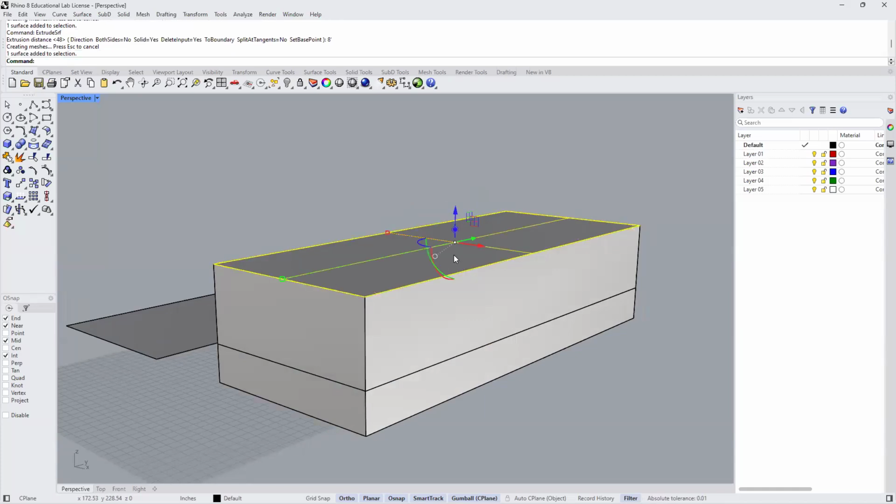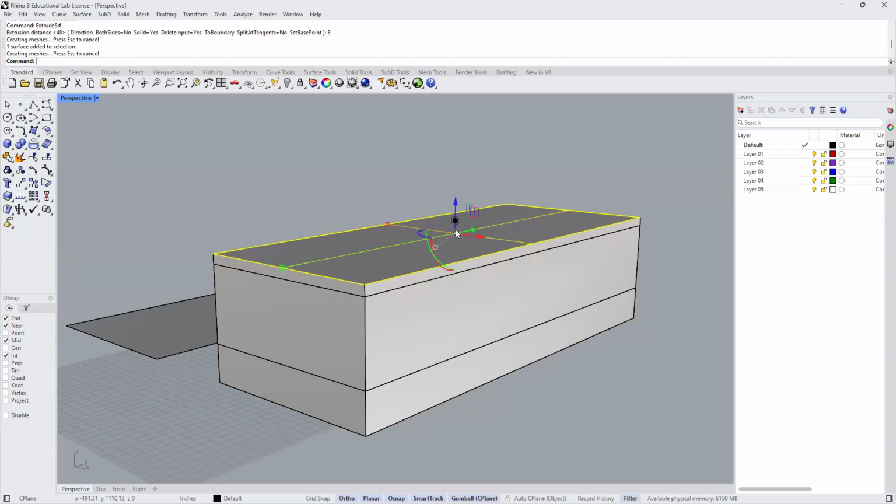All right. So now that I've practiced that a couple of times, now I'll hold down the Control Shift, click on the surface, and I'll use the gumball. And when I use the gumball, I'm going to click right here on the dot, the circle, and notice what it says, that it will extrude it. So I can go ahead and just give that a click. And when I click it, I didn't click and drag, I just basically clicked. Now I need to enter a value. So I'm going to enter a value of 1 foot. So 1 foot, enter.